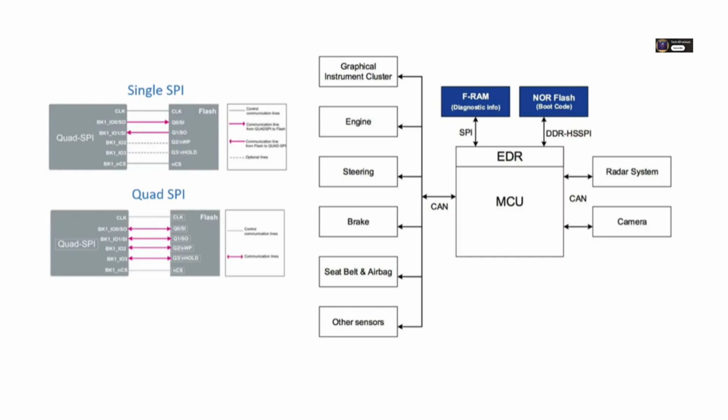Okay. Erase before program. Yes. Then you absolutely must send the write enable command. Just send that single byte. Then pull CS LOW. Now send the page program command byte, followed by the 3-byte starting address within the page. Then send your data bytes, up to 256 of them.